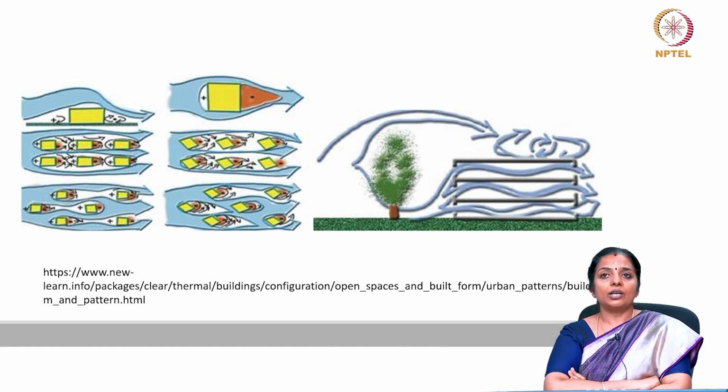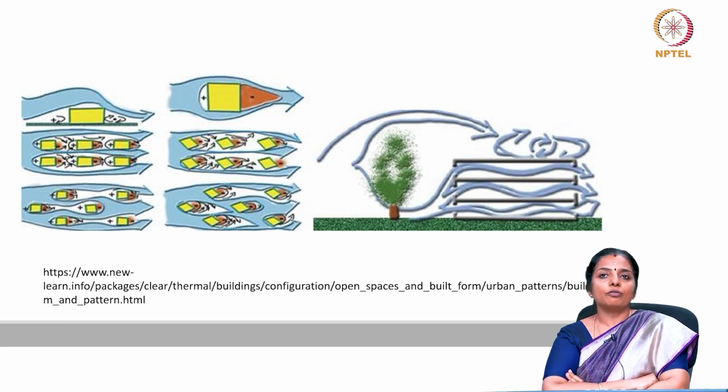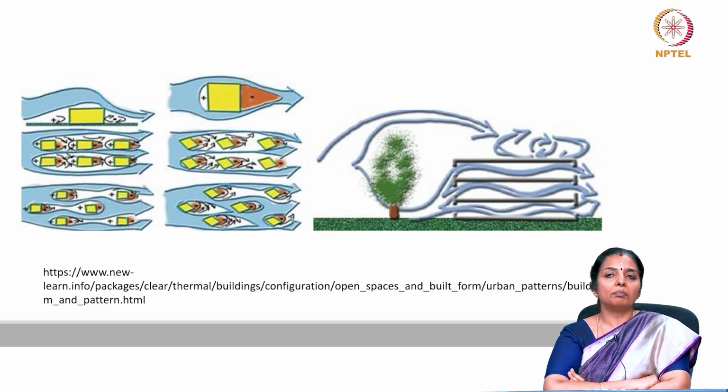When large built volumes or a long row of buildings are placed perpendicular to the wind direction, then shielded zones are established between the buildings where wind speed might be just a small fraction of the speed above the building's roof or in streets parallel to the wind direction. In this case, the distance between the buildings has little effect on the speed of currents between the buildings.